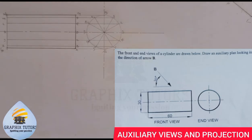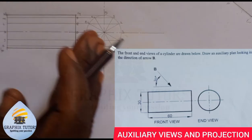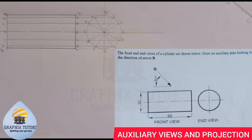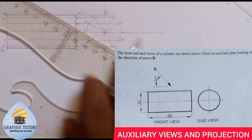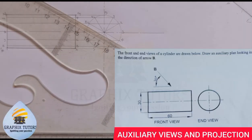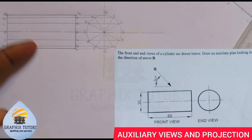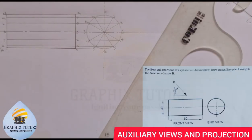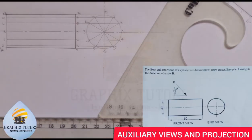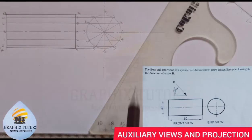Now, if you look at the diagram very well, we're told to look at the direction B from the arrow. The arrow is pointing in this direction. So 30 degrees in this direction. And one thing you need to understand is when my set square is standing this way to the horizontal, this inclined side is 30 degrees. So that is what I am going to project. Place it this way and I'll project it. Since here is 30 degrees, I will use 60. When it's standing this way, it's 60, right? When it's standing in your T-square this way, this is 60. So I will just use the 60 degree and I'm going to project it this way.